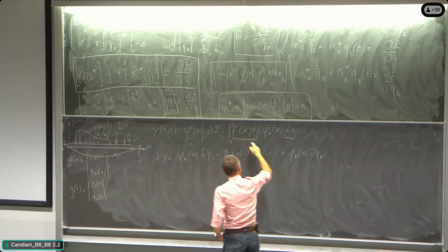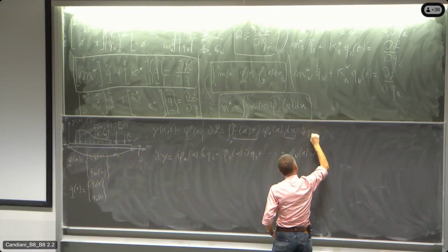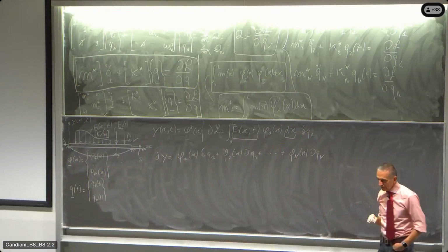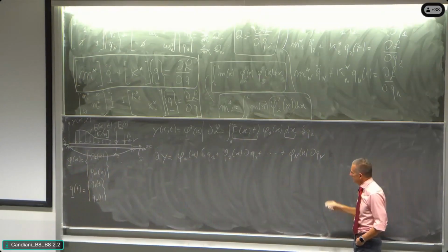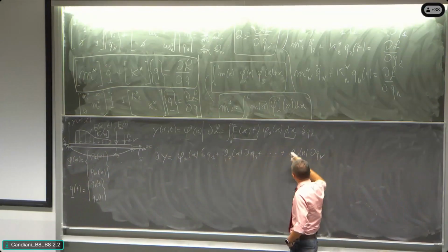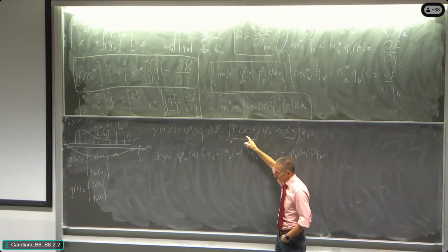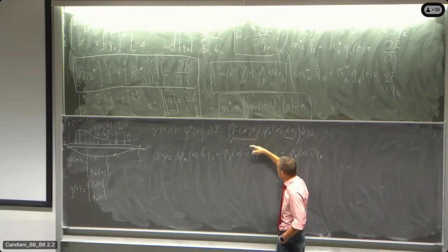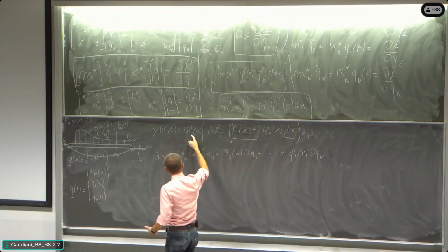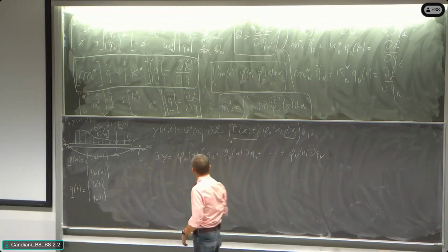But this amount of movement is scaled by delta q1. So the infinitesimal work associated to the infinitesimal displacement delta q1 of the principal coordinate is delta q1 multiplying this quantity. And this quantity is the distribution of force multiplying the displacement. The displacement is the modal shape 1 multiplying the principal coordinate delta q1.